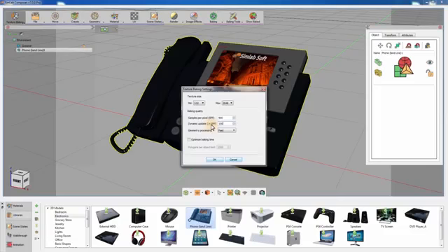The dynamic update controls at which rate the texture baking results should appear during the baking process. So, if it is set to 150 samples per pixel for example, it means that every 150 SPP that SimLab Composer calculates, the texture will be updated and can be seen in the 3D area instantly. And it will continue to do so until the samples per pixel total number is reached and the process is complete.